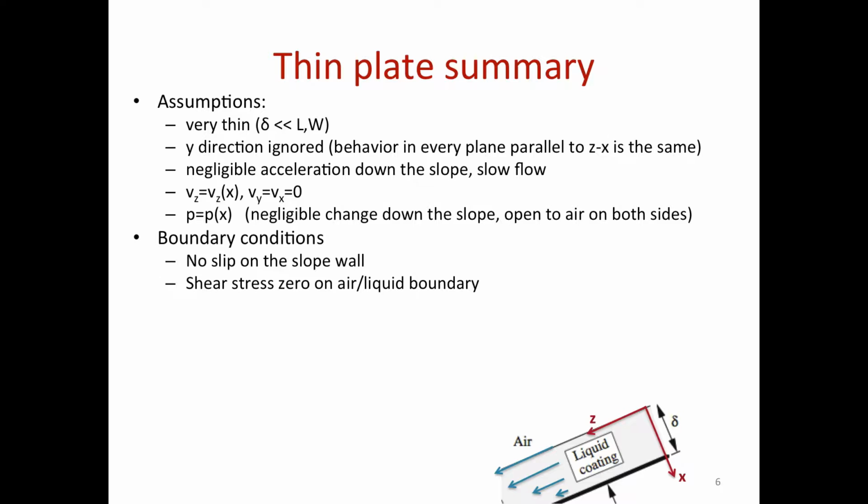Okay? So whether you have an open boundary or a closed boundary will really shape this flow. So think about it this way. Here I have air, and therefore I have only a half parabola. Okay? If I had a solid wall, I would have a full parabola. And that would really change my profile, okay? And overall, the flux going through. So putting any kind of wall as a boundary will shape your solution and ultimately really change the flux going through.